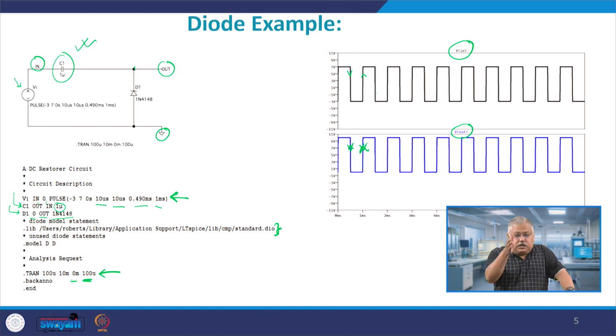When the input is sharply changing, that is the point when the capacitor is almost like an open circuit, and therefore, whatever input you are giving is appearing in the output. That is the reason you see the top and bottom curves emulating each other.